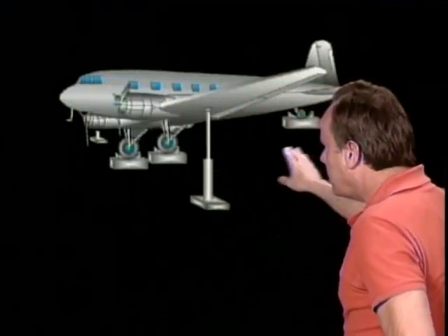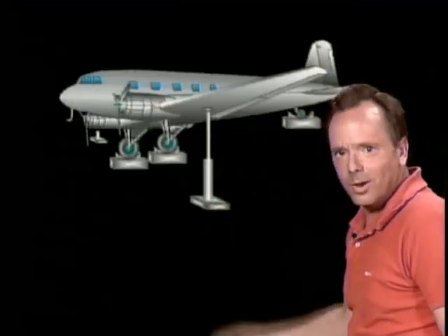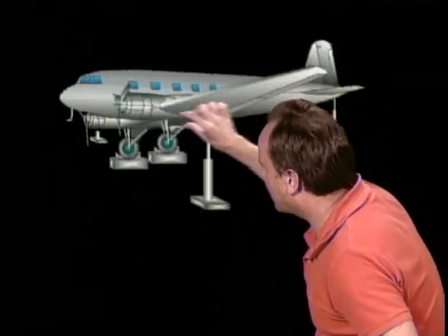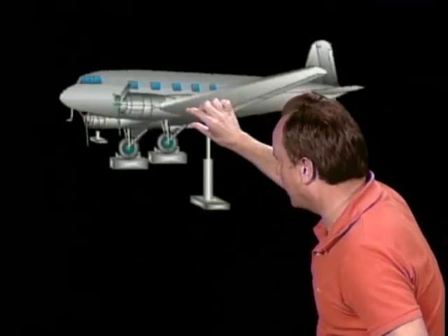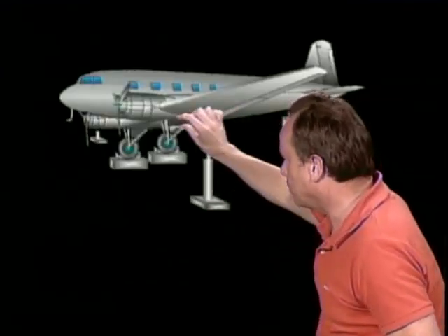Now let's assume you want to jack up an airplane to weigh the aircraft for weight and balance purposes, and you're going to do it with a magnificent DC-3. The question is, should you do it indoors or outdoors? And they want you to generally jack up aircraft for weighing indoors. They don't want the wind to affect the weighing of the aircraft. And also they want you to know, before you jack an aircraft, you need to reinstall any critical stress panels or plates, because if you have plates off the aircraft that are load-bearing stress panels and you jack up the aircraft, you could put a stress on other parts of the aircraft that it's not designed for.